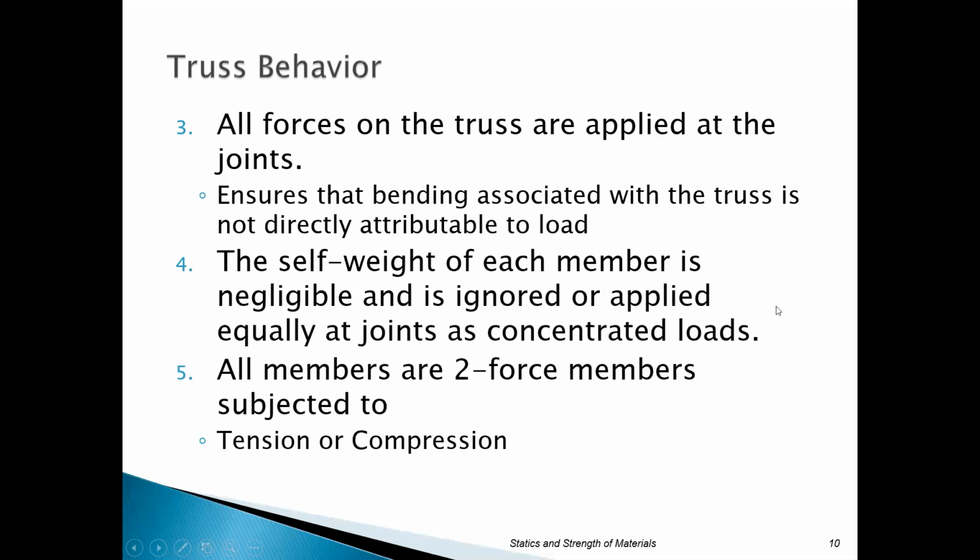So what you're doing is you're applying it through the concentrated loads themselves. Okay, we know that those members are extremely heavy, but the way that structural engineers look at it, they put it into the actual weighting of the concentrated loads. And so all members then are subjected to two-force kind of thing, either tension or compression.